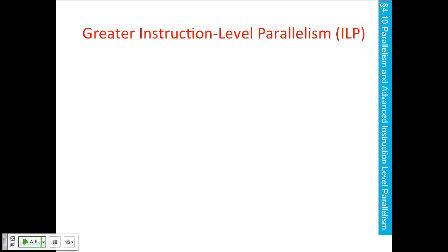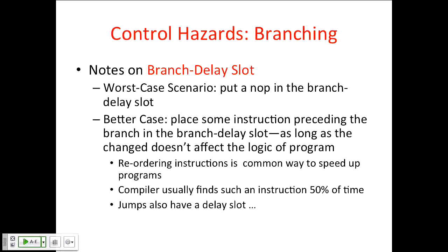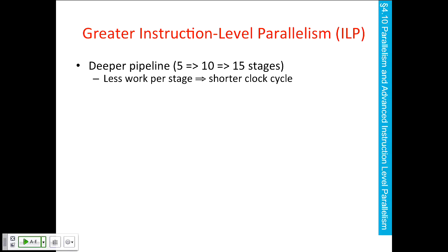Okay, so this is just a sort of introduction to pipelining, 61C. And I got a question at the break. This kind of material was really developed in the late 40s, early 50s, this kind of pipelining. And architects have been busy ever since. And so some of the things you'll read about go into even deeper pipelining. So we just looked at 5 stages. Some processors went up to like 30 or 40, well, mid-30 pipeline stages to execute one instruction. And somewhere in the middle of there will be the integer add, taking one clock cycle out of 30-something.